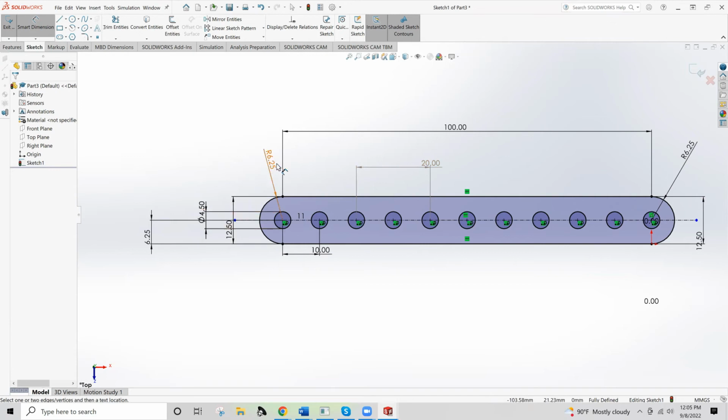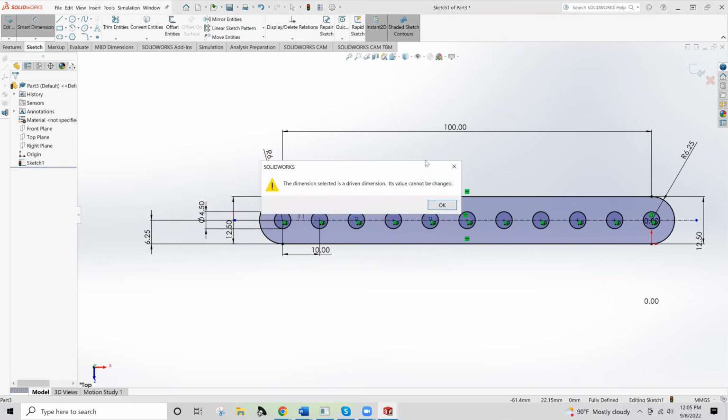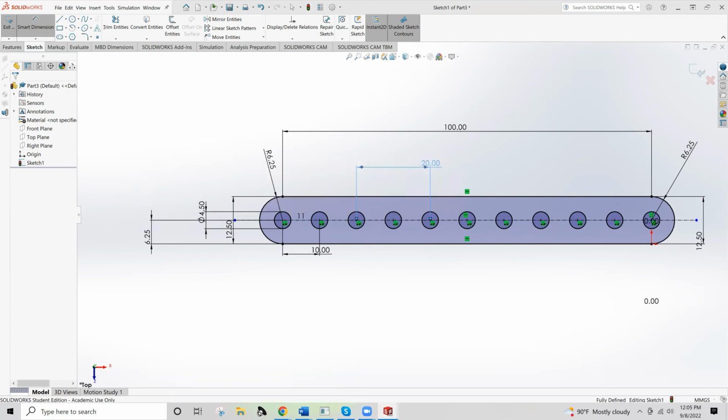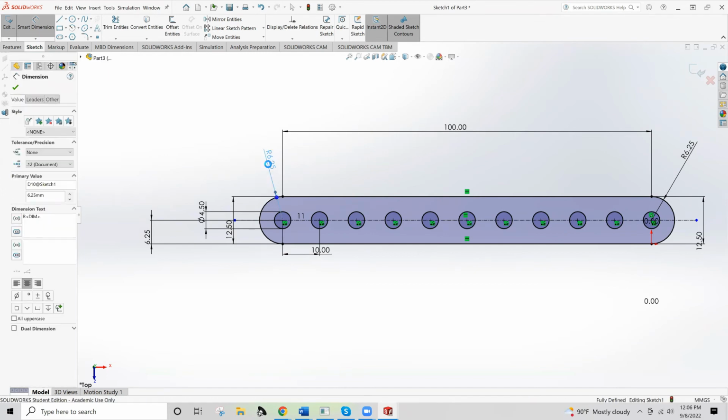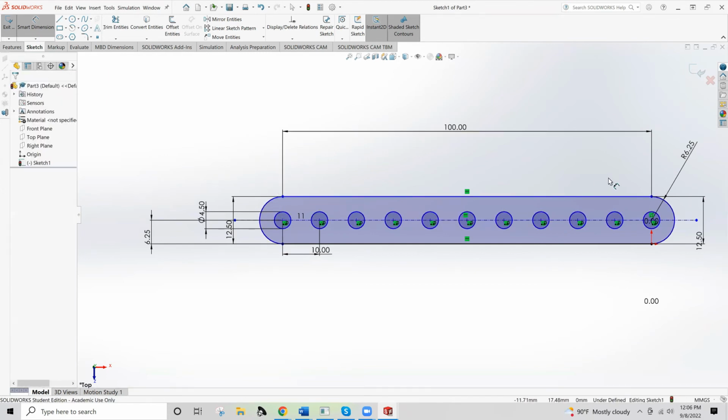Really, for full definition, you can go in and delete them. For this, I don't actually think you need the radii. Yeah, maybe I guess you do need both radii, because you need to set a couple of those key points. Probably because you need to specify that this isn't a farther arc.